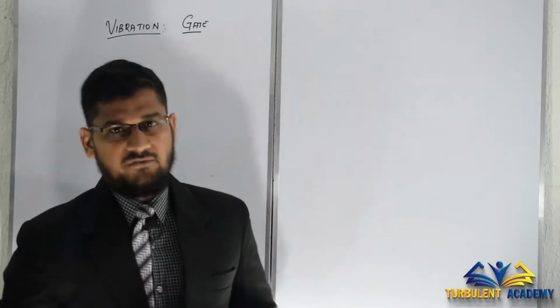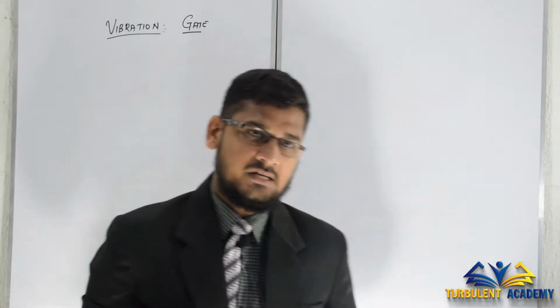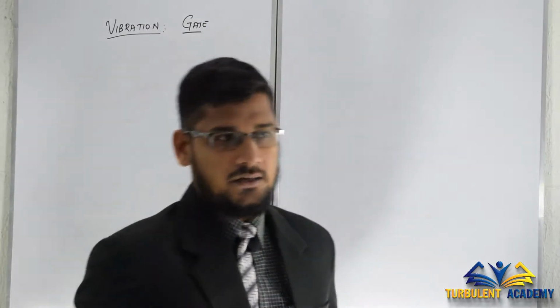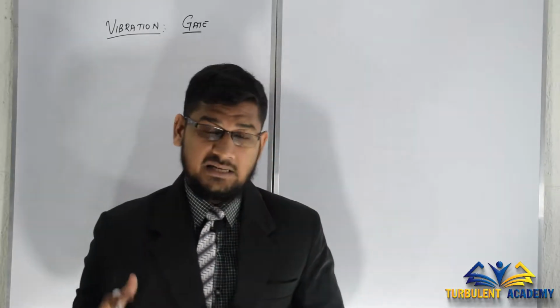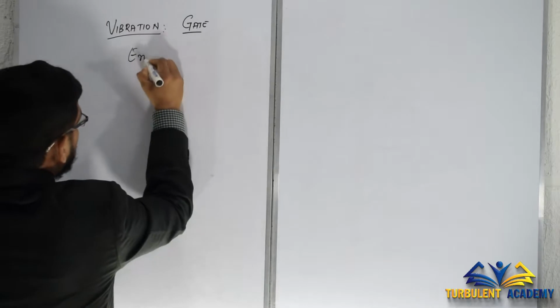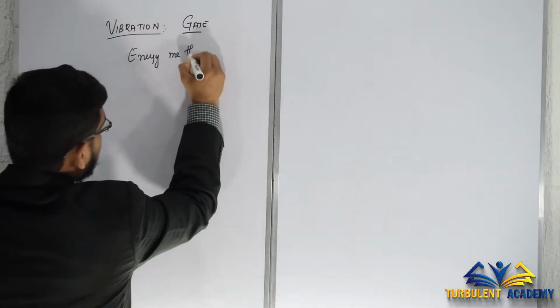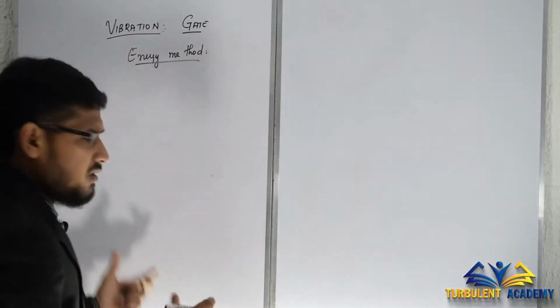Fine. Before going into the first problem, we'll find out the ways and means to calculate the natural frequency, because we have lots of methods like simple harmonic motion, Newton's law of motion, energy method, Rayleigh method, D'Alembert's principle and all those. Right now we are going to concentrate mainly upon one particular method, which is used to solve about 90% of vibration problems, which is the energy method. Okay, so we'll see what an energy method is. Mostly you will be able to solve problems using the energy method.